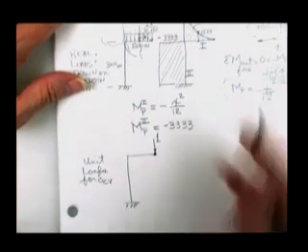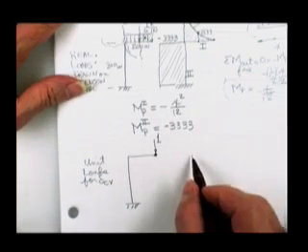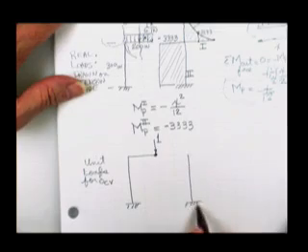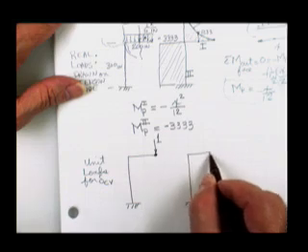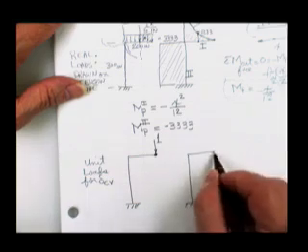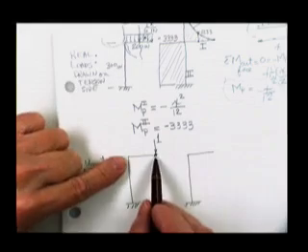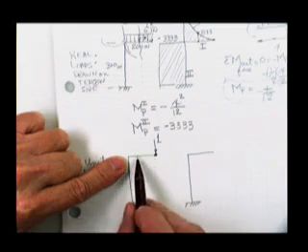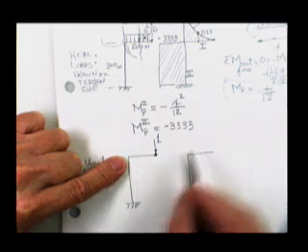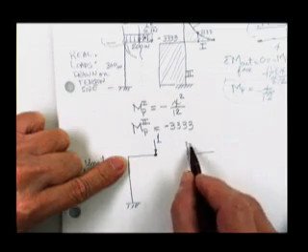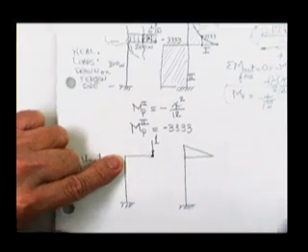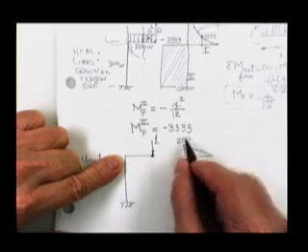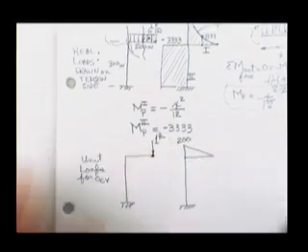All right. Here's the moment diagram if you would like a picture of it. Looks like this. The moment diagram is 0 here, 1 times 1, 1 times 2, 1 times 8, 1 times 40, 1 times 200, and therefore the moment diagram looks like that. And that value reaches 200 kip inches.